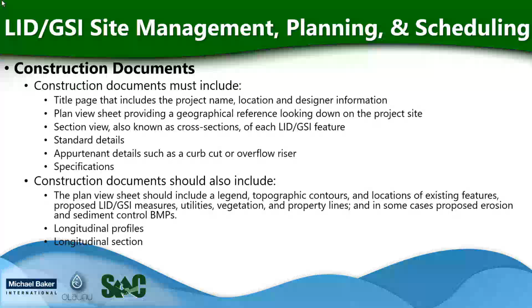Standard details provide a detailed view of critical elements such as a LID GSI measure. A pertinent detail such as a curb cut or overflow riser should also be included. And then specifications, which provide written detailed information on materials used on a construction project as well as the proper technique required for installation and construction. Those are the critical elements that must be included.